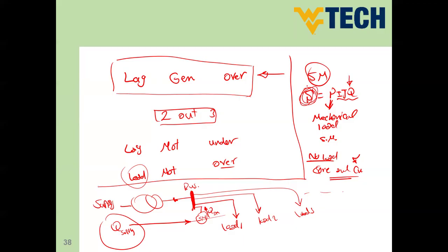So if I take this motor from the store shelves and just connect it to the supply, controlling the power factor of this motor to work as lead, I can have almost Q equals S if we neglect the losses. So Q is going to be the same as S, and this motor will provide reactive power and work to compensate or improve the power factor of my system.